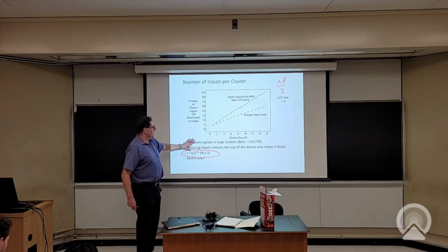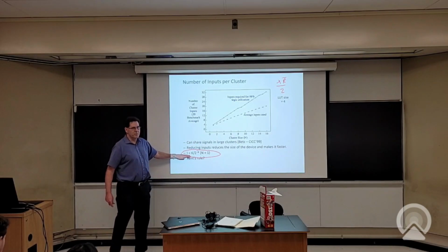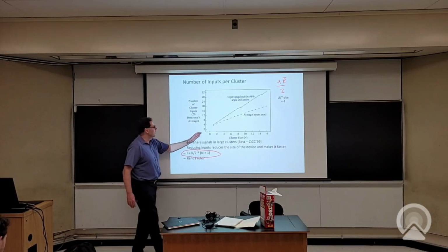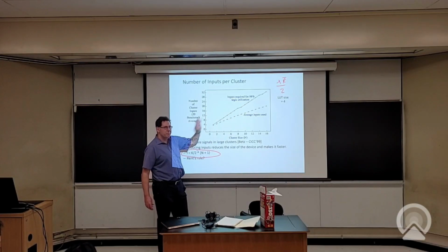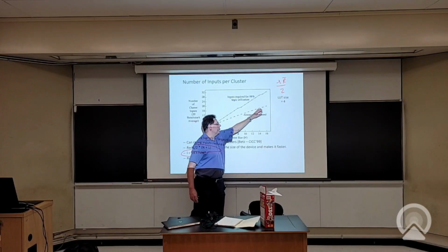And if you give it a constraint, you say, well, the most inputs you can have is this number I, and it's about half the total LUT inputs, it's okay. It actually can pack the logic blocks full. That's what this black line is showing. And the average number of inputs grows even more slowly.